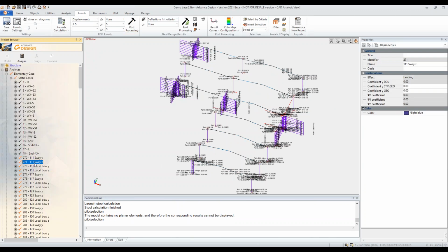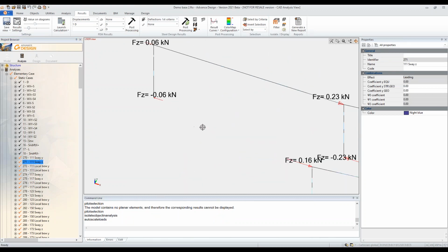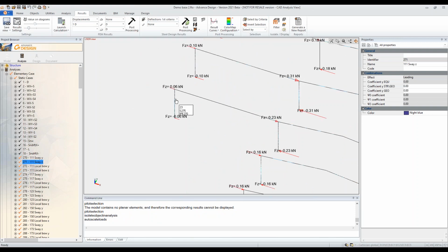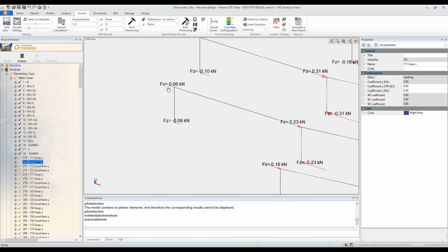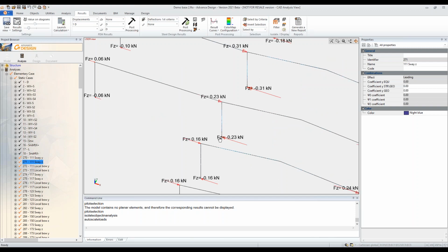Like, yeah, this one we can isolate. And you see, you get the expected global imperfection forces. It's a punctual load on top of a column, which is balanced by a punctual load at the bottom. And this intensity depends on the actual force. So it will be smaller for a column on the far left and a bit bigger for a column in the middle.